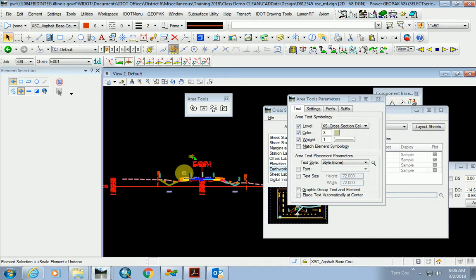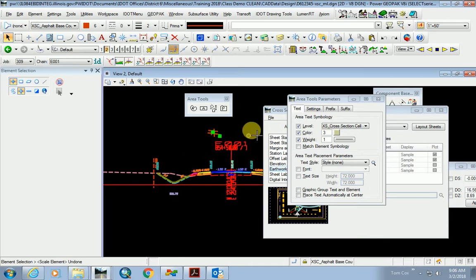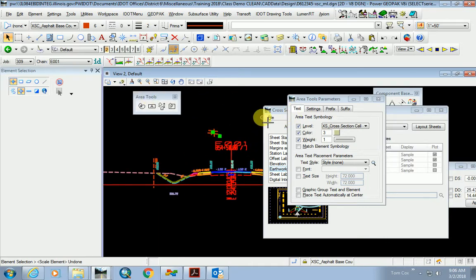You'd just flood it. Now here's what I would probably do instead, just like what Tina did the other day. She wanted square yards, and it gives you the working units, which are square feet. Yeah, they wanted me to switch it to yards. So just like you did in the plan view, you can do that with cross sections.